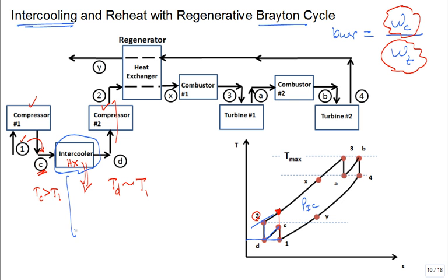So you try to cool it back down at high pressure and then feed that into the engine. You can pack more oxygen into that displacement volume of that internal combustion engine. And hence you could stuff more fuel in there, get more bang, get more power. That's why turbocharged engines work that way. But they work a lot better with the intercooler. Okay? So cool it down so you can pack more oxygen into the cylinder. Same with the supercharger. Instead of having it driven by the exhaust gas, the supercharger's taking mechanical energy off the crank to boost the pressure. All right.